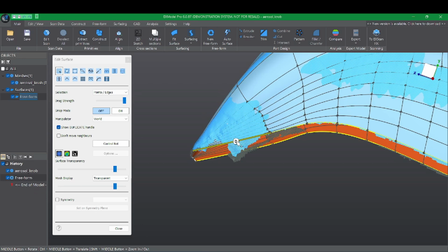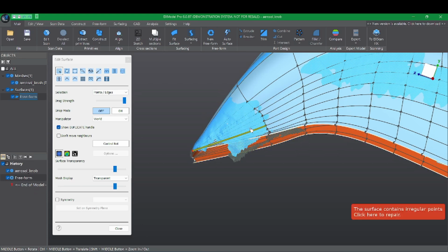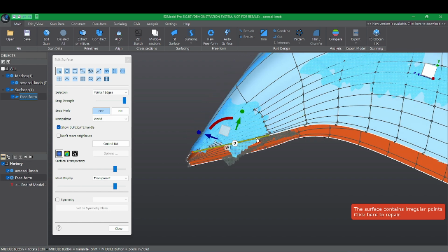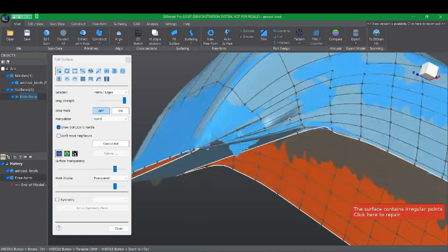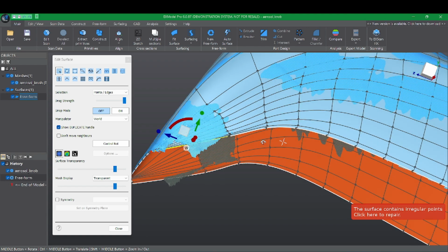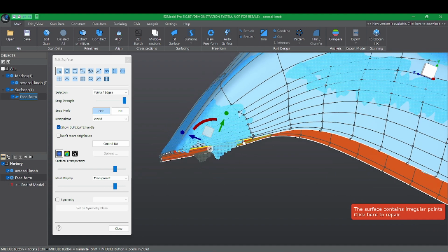And be careful that if I place in this view, be careful that when you move a mouse, if it highlights, it actually will snap the mode to this point, regardless of whether the snap mode is on or off. So if I leave this here, you see that we get a worse result.